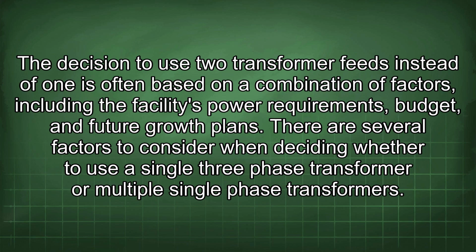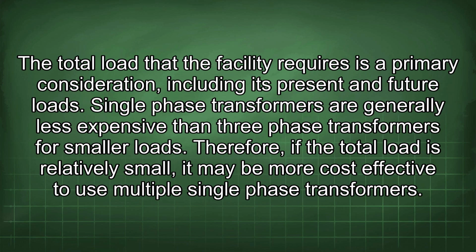There are several factors to consider when deciding whether to use a single three-phase transformer or multiple single-phase transformers. The total load that the facility requires is a primary consideration, including its present and future loads. Single-phase transformers are generally less expensive than three-phase transformers for smaller loads. Therefore, if the total load is relatively small, it may be more cost-effective to use multiple single-phase transformers.